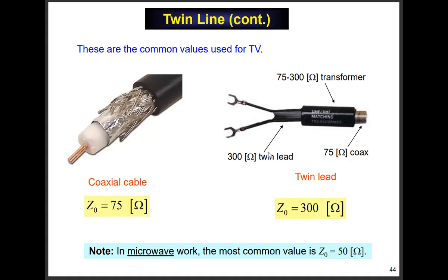And if you believe what I just told you, if the signal is coming along, let's say on the 300 ohm line, and it just hits a 75 ohm line directly, there'll be power reflected, right? So you want to have a matching transformer that changes the 75 ohm impedance to 300 ohms. So the signal coming on the twin lead thinks it sees 300 ohms here, so there'll be no reflections. That's the job of this. It's a matching transformer. And in a later set of notes, we'll talk about matching transformers and all that kind of good stuff. But not today.